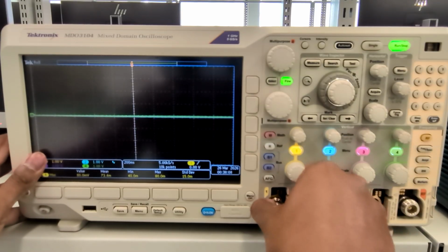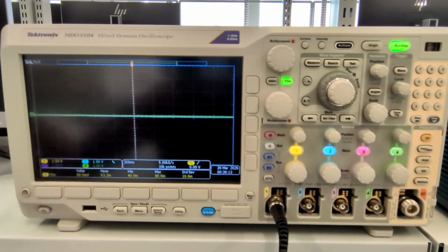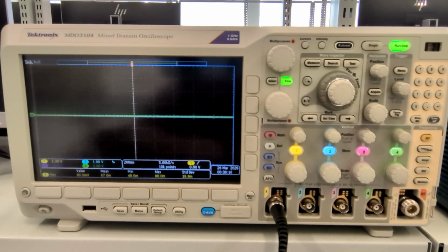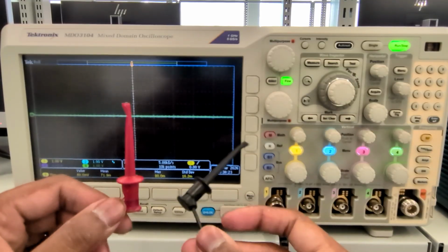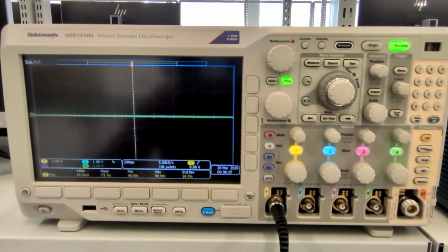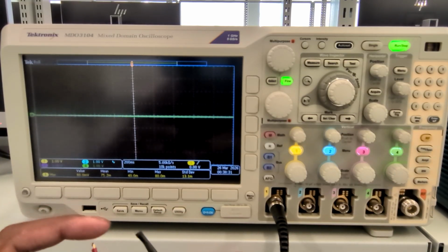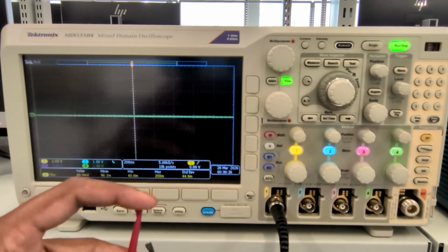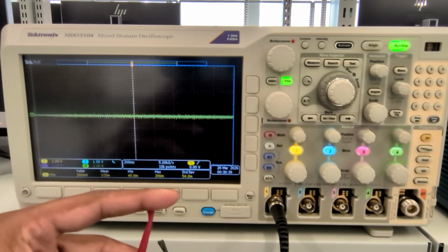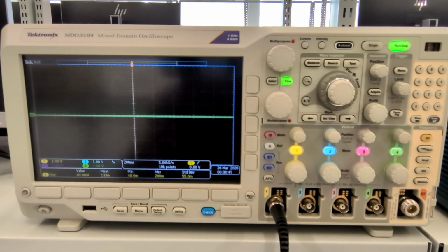And then, while still pushing in just a little bit, we turn to the right until the connector stops turning. You'll feel it kind of snap into place. And that way, we know that our lead connector is locked in. Now, these two leads are actually used as an input for our oscilloscope. And I can kind of play around with this to just show you that it is actually measuring something, by maybe touching the positive lead on the oscilloscope with my finger. And this is measuring some very small electrostatic voltage that's on my skin. So now let's see how we can actually use this to measure various different input signals.